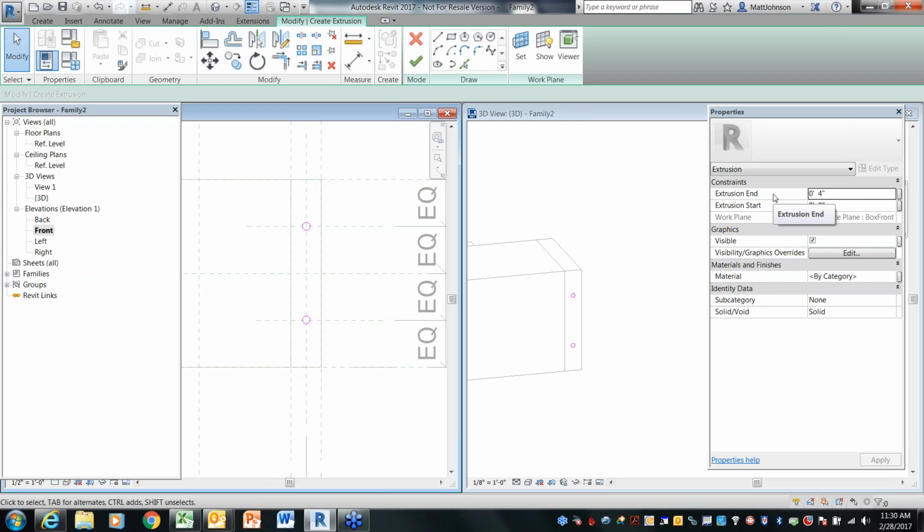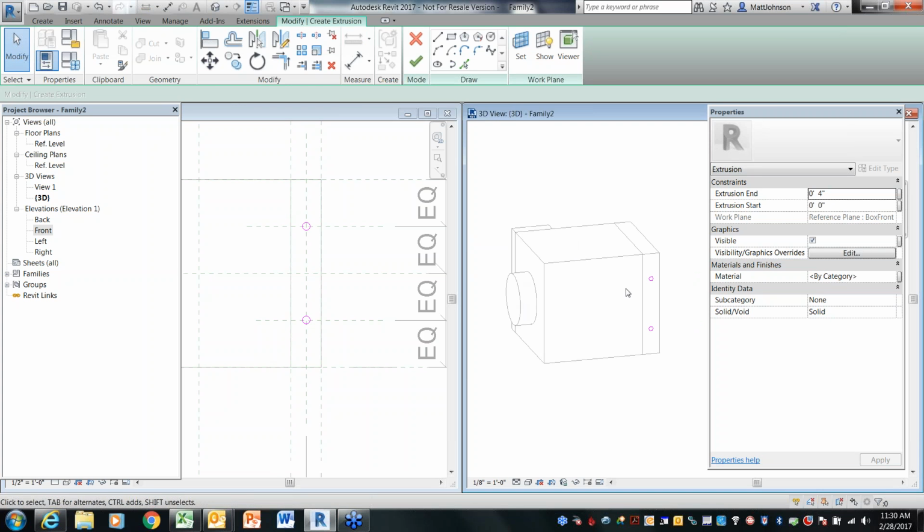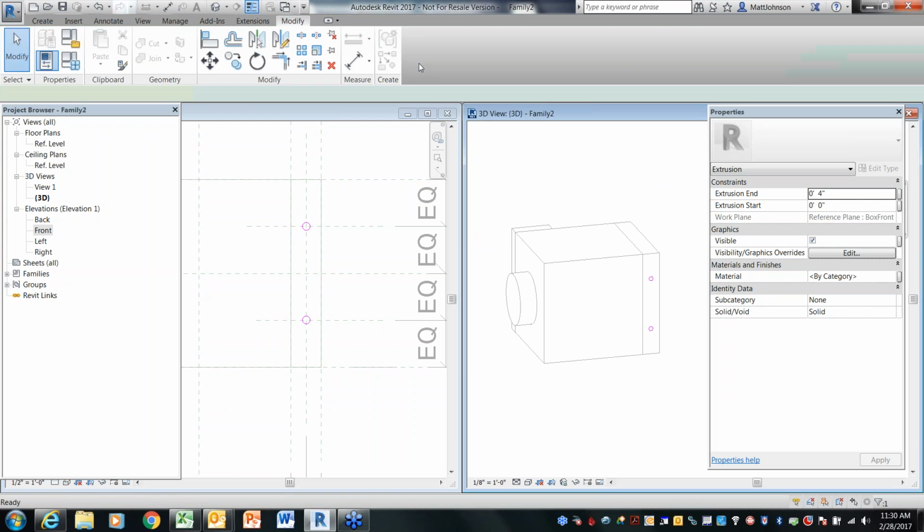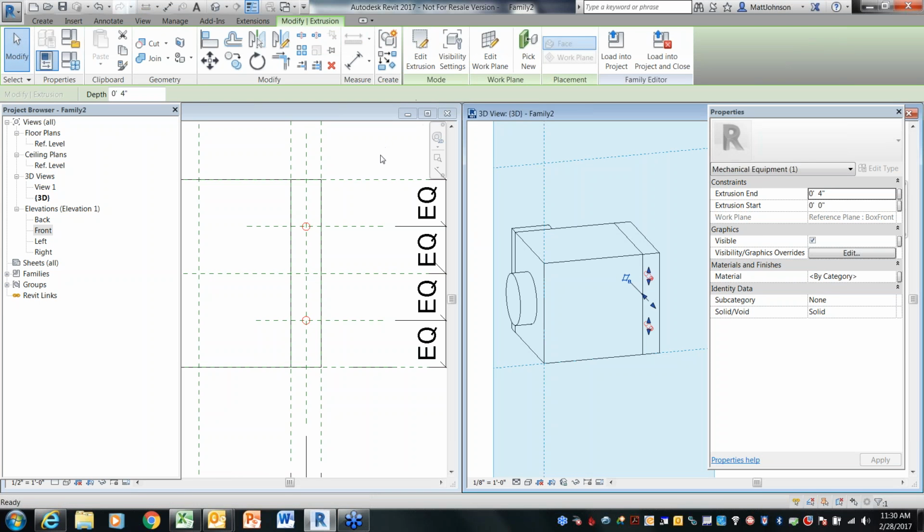And then it'll just give you a face a little bit offset from the box or the reheat coil, so that you can attach your thing. So that can stay. That doesn't have to be parametric. If you wanted it to be, you could do the same thing that you did over here with the duct length and set the pipe length as well. But for our purpose here, we'll just go ahead and make them always 4 inches. Okay?